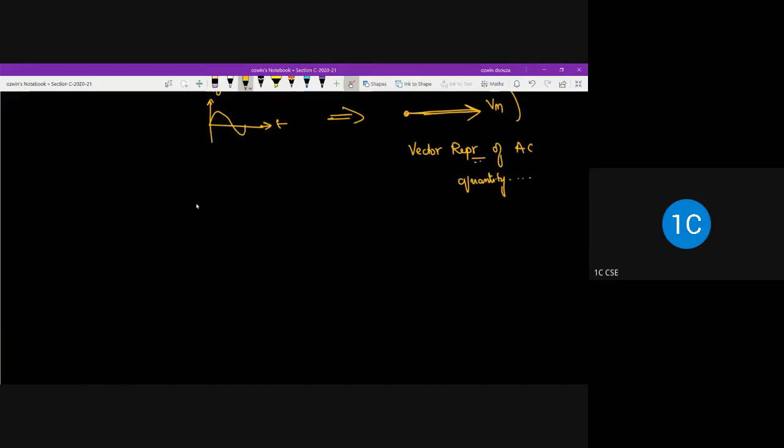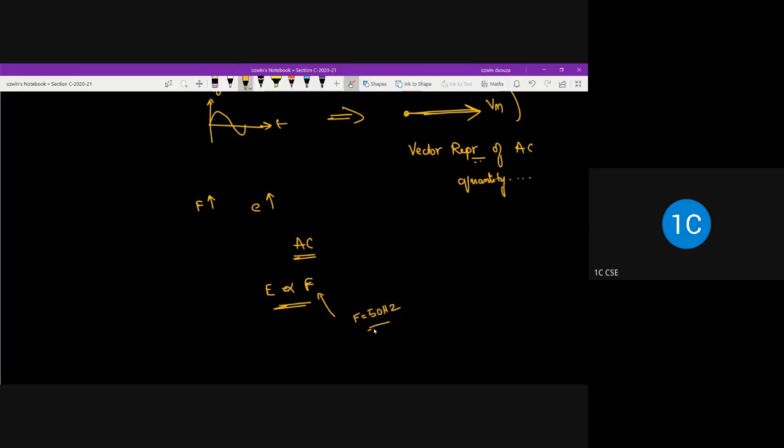Now, with the increase in frequency, the EMF can also be increased. That's because in case of an AC generator, eventually you'll see in module 4, your induced EMF is proportional to frequency as well. But we will not change the frequency because at the destination, our systems have been developed to receive a frequency of 50 hertz.